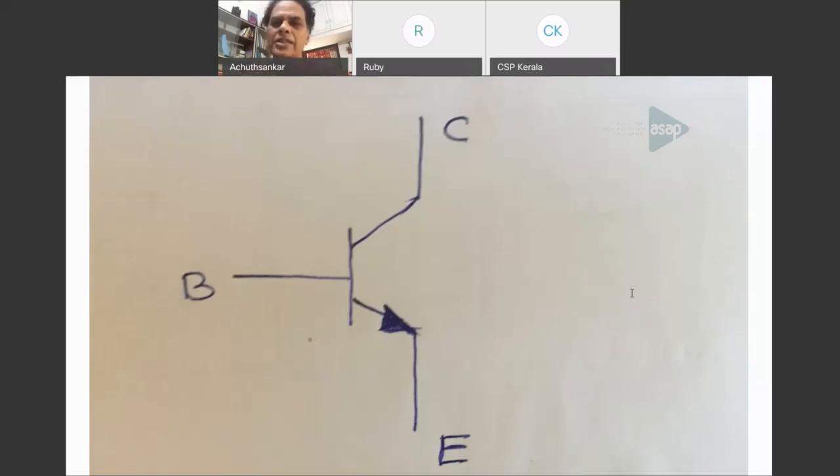So for a diode, the answer is actually the diode is a resistor. The diode is a resistor, but a very strange resistor. If you measure the resistance from the left to right, the resistance is 0. And if you measure the resistance from right to left, the resistance is infinite. That is the difference, but it is still a resistor. We would have to say its model will have to be written in 2 parts.